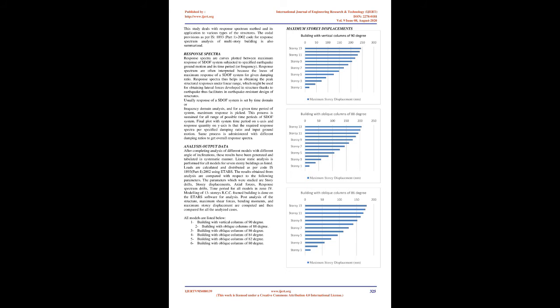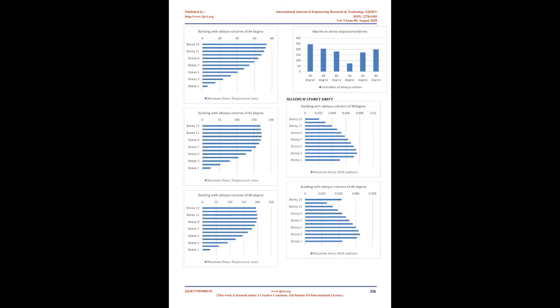The concept is a dynamic analysis into partly static and partly dynamic for locating the maximum displacement. It is restricted only to one mode of vibration of the structure. Response spectrum analysis is a method to estimate the structural response to short, non-deterministic, transient dynamic events. Examples of such events are earthquakes and shocks. Since the precise time history of the load is not known, it is difficult to perform a time-dependent analysis. Because of the short length of the event, it cannot be considered an ergodic, stationary process, so a random response approach is not applicable either.